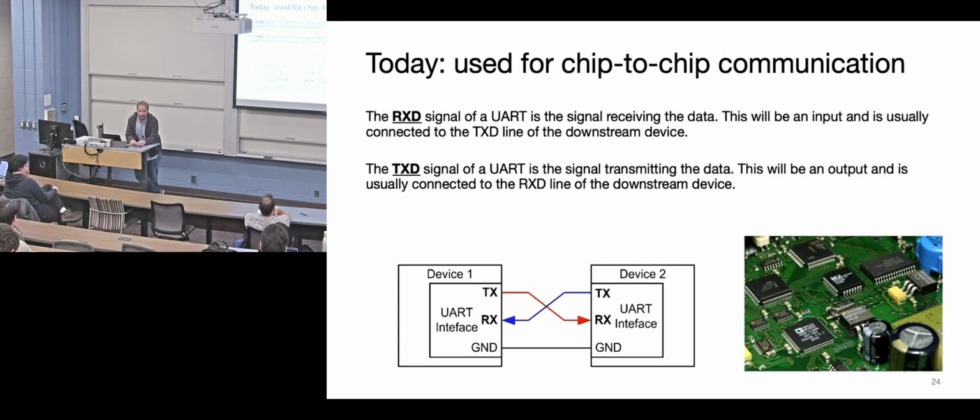Yep, exactly. So for the base timing, you have to actually enter it in. A priori, both sides have to figure out the baud rate, which is basically the width of the symbols. But then you don't know when the symbols are going to happen in time. So we do the oversampling trick to figure out where the first edge is coming in. If I know where the front edge is, I'm going to sample precisely in the middle of each one of those bits.